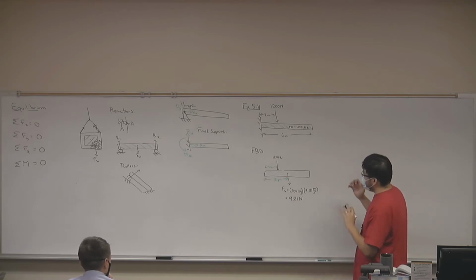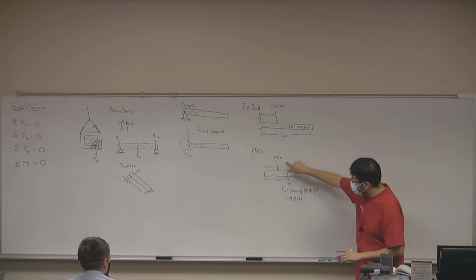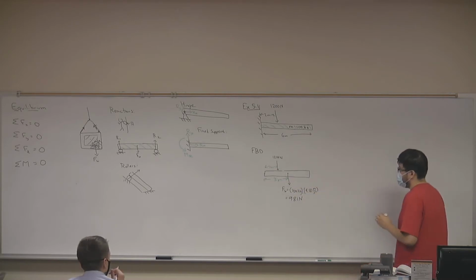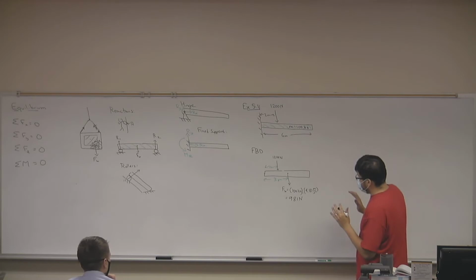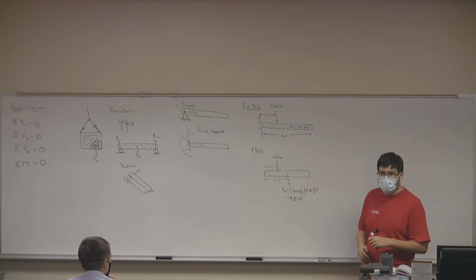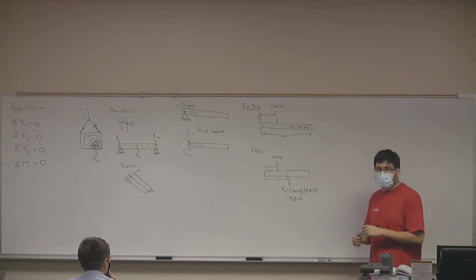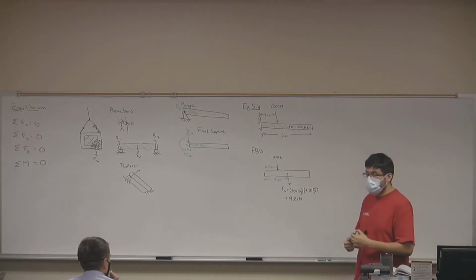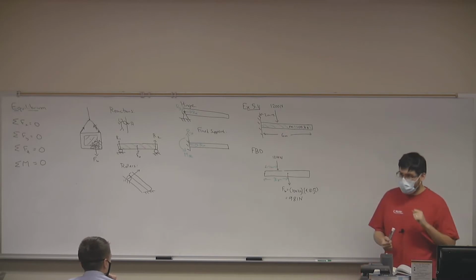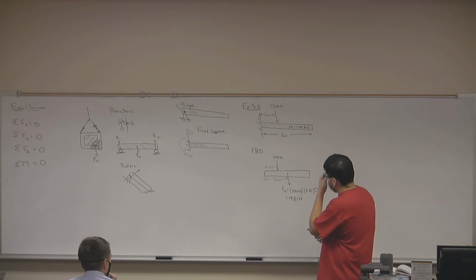So what we have is a system where I'm looking at body forces. I'm looking at a surface force or impact force. But right now, if I look at it, this doesn't really look static. I have two forces. They're all pushing this beam downward. But this is a static beam. So what am I missing now? Reaction force. Reaction force, right? That's a key word. Good. So we're missing reaction forces.